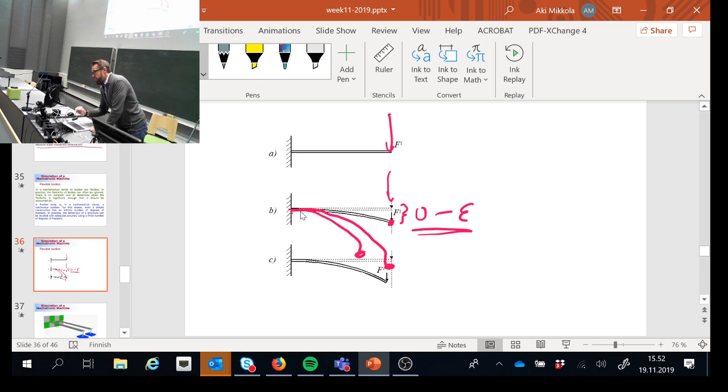What's the difference here is that there is a certain amount of deformation in the axial direction, and that you can only capture by having a nonlinear strain-displacement relationship. This is something that, when you look at the literature, is called geometrical nonlinearity. That's what it is called. Now, in the studies we're doing in my team, we assume that relation to be, of course, nonlinear. Then we can capture that large deformation.